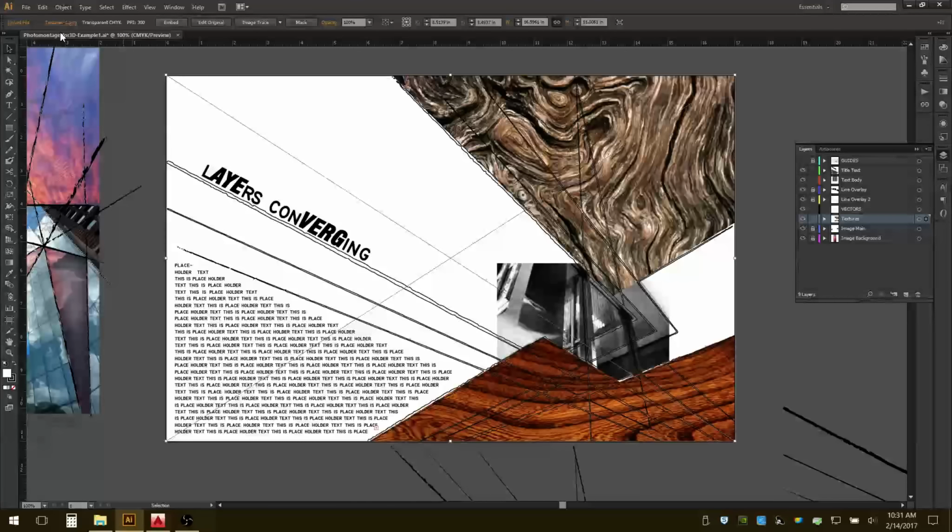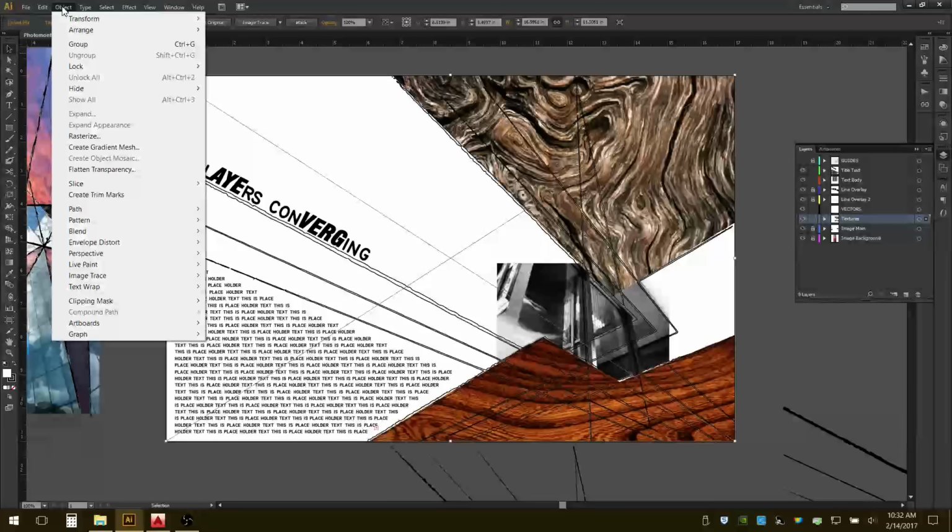Okay, so the exercise brief references, it's the first step, live trace, and that's what it used to be called, and so that's a bit of an error. It's actually called image trace in the newer versions of Illustrator. So if I go into Object, now I have the texture selected, Object, down to Image Trace, and basically what it's going to do, it's going to move through this image and try to discern some pattern or texture of vectors that are relative to that image.